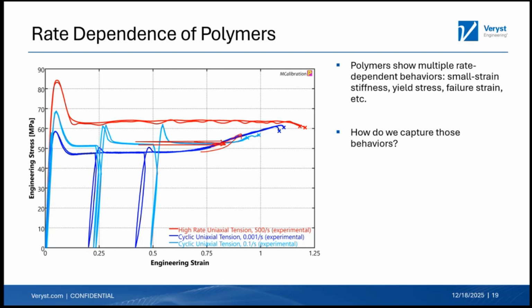They have essentially similar material models, but what you need to do is give them failure strain versus strain rate, because you can see strain-rate-dependent failure. Here we don't see a huge effect in this particular material, but then the other one is triaxiality. Triaxiality is a scalar to look at the stress state. It is the pressure over the von Mises stress, or maybe the negative of the pressure over the von Mises stress, depending on how you define pressure.